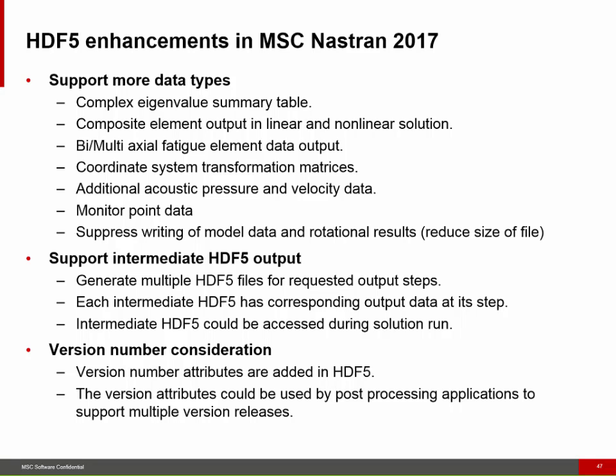You can also, from Solution 400, generate intermediate HDF5 files so that you can post-process during the time the simulation runs. So those are the major things we add in 2017, but we continue to add stuff also for next version. So this is, as we see it, the format of the future for MSC Nastran results.